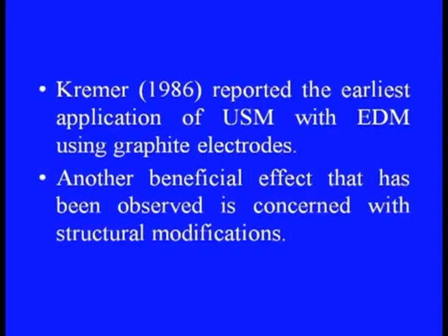It provides ideal conditions for discharges and gives a higher removal rate. Kramer in the year 1986 reported the earliest application of ultrasonic machining with electric discharge machining using graphite electrodes.